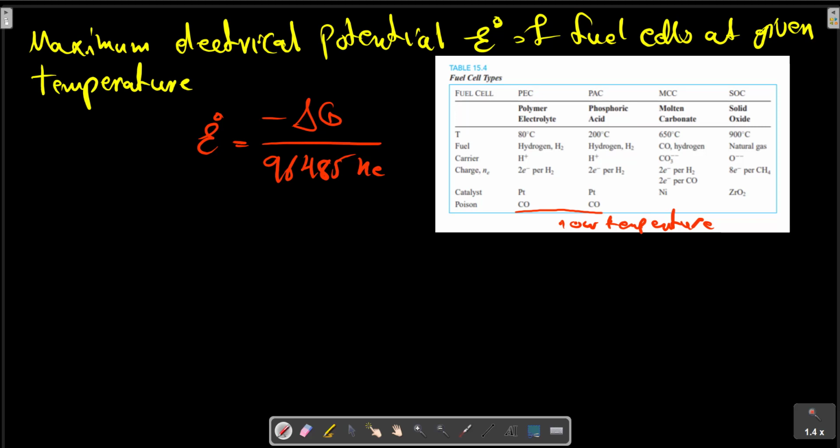A model can be developed for the various processes that occur in a fuel cell to predict the performance. From the thermodynamic analysis, we found the theoretical voltage created by the process, the EMF, from the Gibbs function. At both electrodes, there are activation losses that lower the voltage and a leak current, shown with I leak, that does not go through the cell.